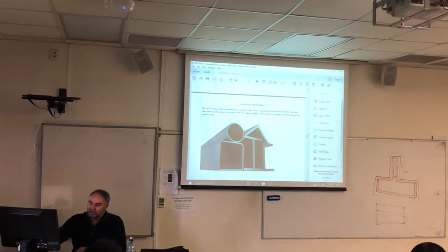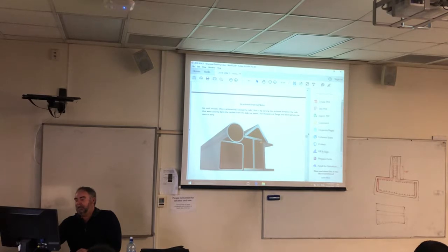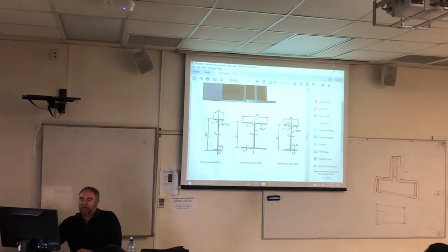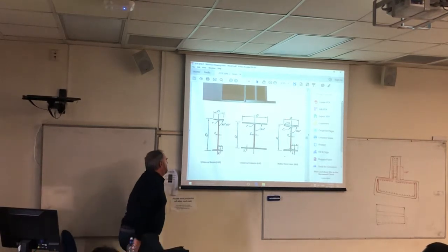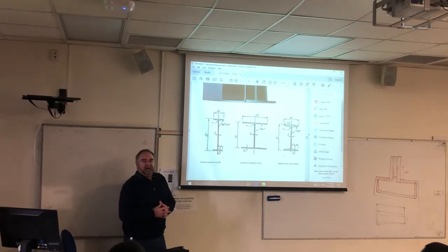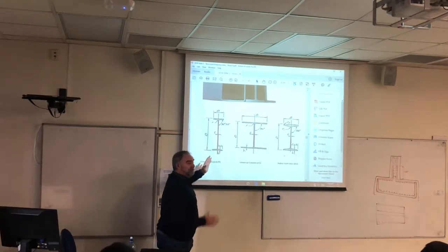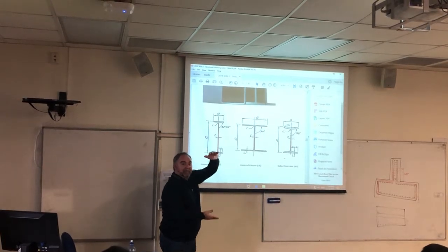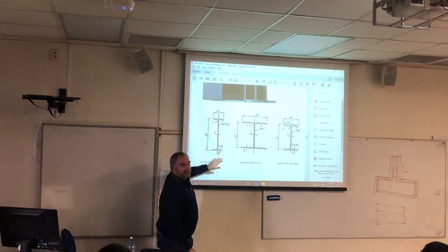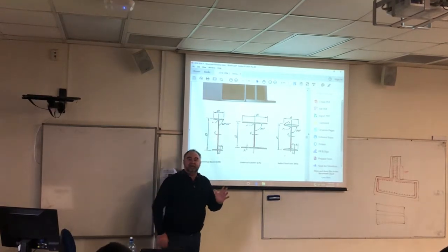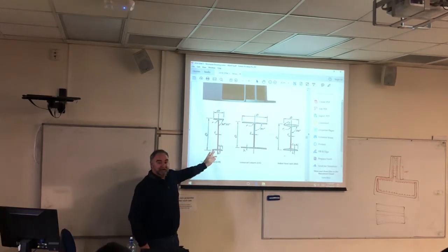This is an angle. This is possibly a column rather than a beam. This is a flange, and those are hollow core beams or steel members. Here's a profile shape of them. This explains it a little bit better. A universal beam, or a UB as they're called, is quite a bit skinnier than it is height. The height is always quite a lot higher than the width. They do come fatter than that, but generally speaking, you'll recognise a beam because it's more like that shape.